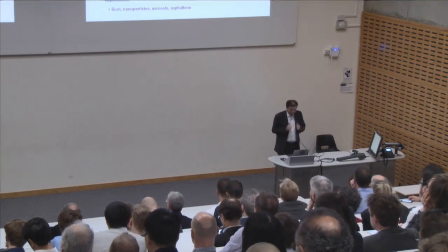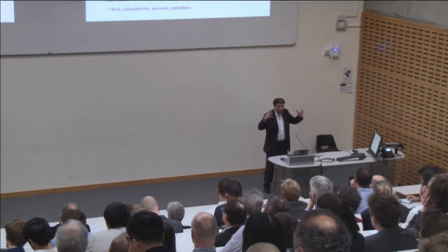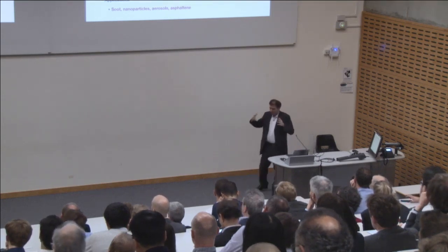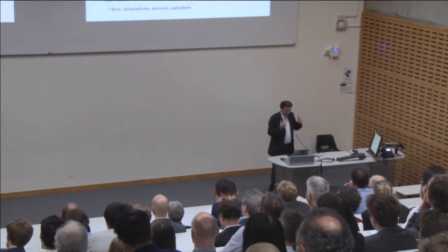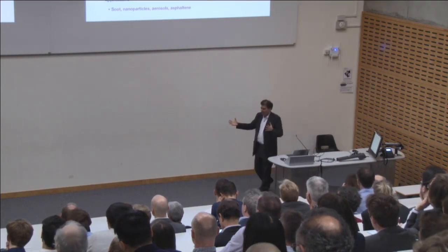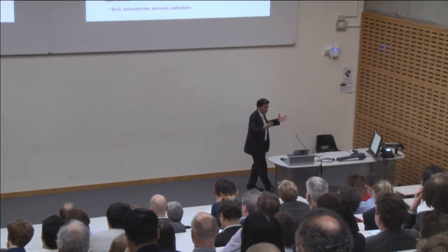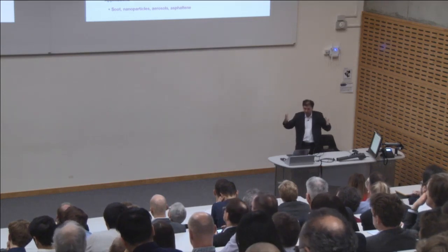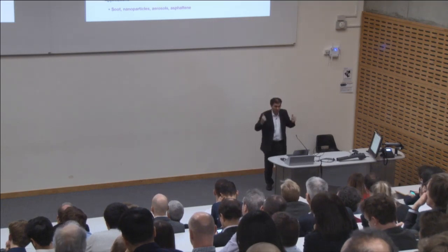Now, having had these methods, how can we couple this with fluid dynamics? This is very difficult also, and I must say that for a long time, the community believed that this would be a too expensive problem, computationally expensive. So the approach generally was to simplify either the fluid dynamics aspect of it or the population balance aspect of it. Simplifying fluid dynamics means to consider the system as either fully mixed or a network of fully mixed zones. Simplifying population dynamics means to consider it, for example, as monodispersed.